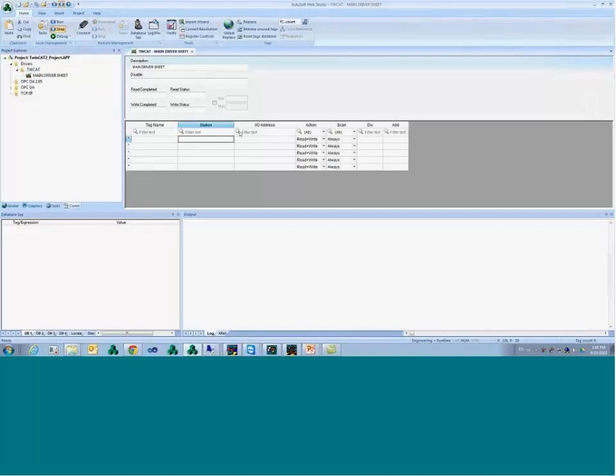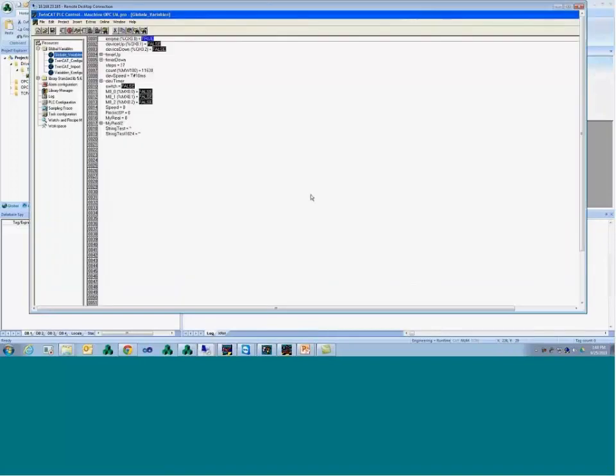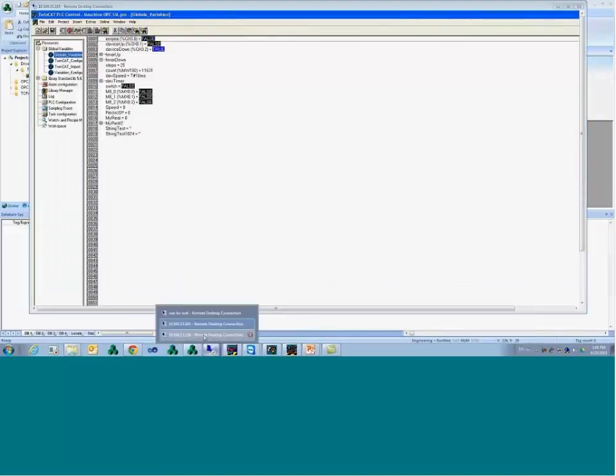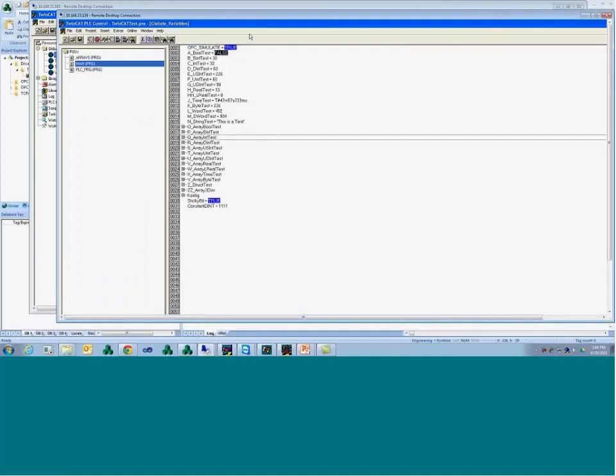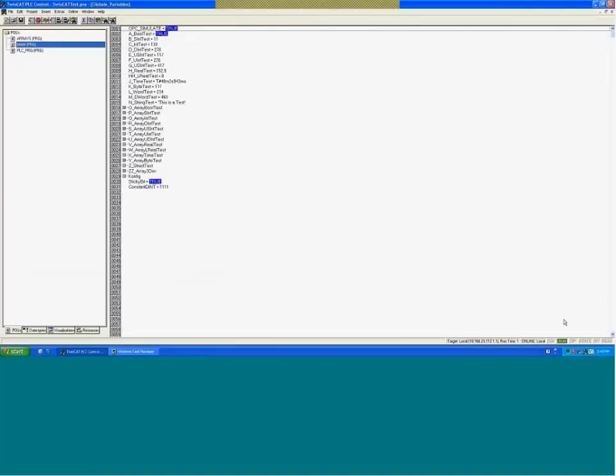Then I have the main driver sheet by default, and I can add standard driver sheets as I want. So let's configure the main driver sheet first. I'm not tying it to the tags anymore like I was with the tag integration, so I have to say where my PLC is. For this demo, I'm going to communicate with a PLC that is running on this other computer here, where I have those variables constantly changing values, and I have this OPC simulator running.